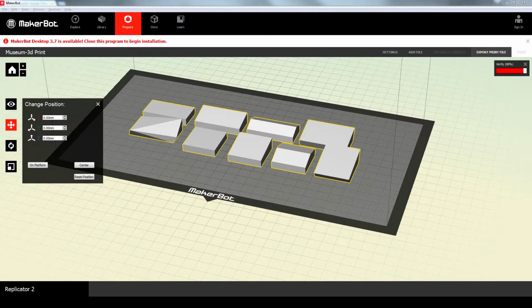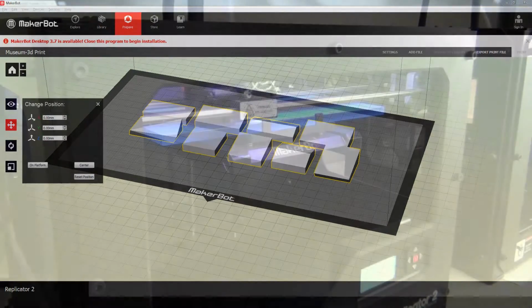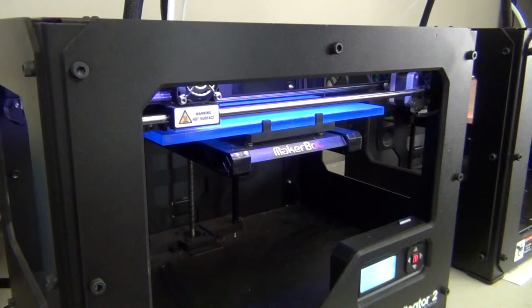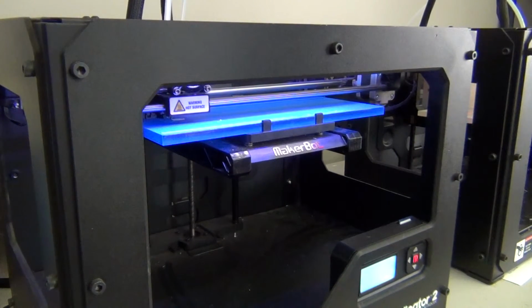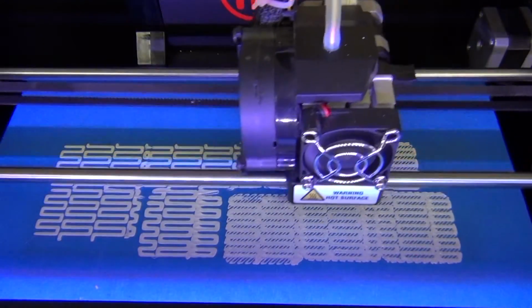There are a few things that you can do to get that print to happen even faster. One of the things that takes a while is the infill. This is set to a 10% infill, and that is basically the hexagonal mesh that's going to happen on the inside of each one of those building massing forms. I can set that to 0, except the problem is the roofs aren't going to work very well. But at times, if everything's flat, if I have a flat roof or a single sloping roof, I can flip everything upside down and basically print the roof first and then the walls.